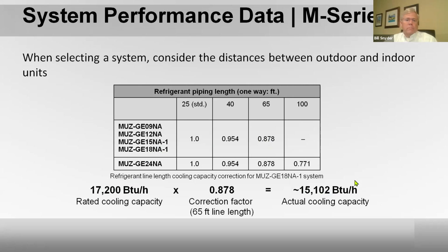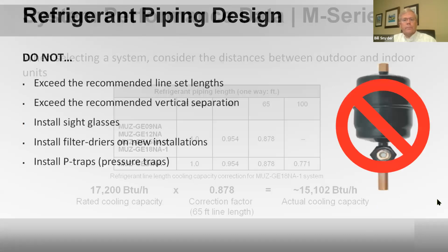It'll work fine some of the year, but if your design conditions are, say, 95, on that 95-degree day, it's not going to handle it. You're going to get a phone call. So you should be aware of this. If you install them with the short line lengths, you pretty much stick with the rated capacities.